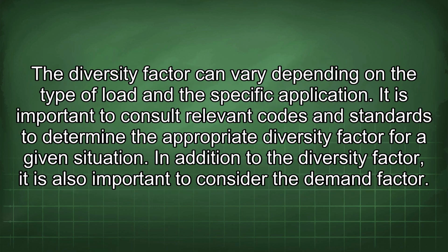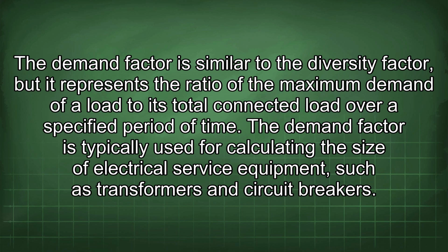The diversity factor can vary depending on the type of load and the specific application. It is important to consult relevant codes and standards to determine the appropriate diversity factor for a given situation. In addition to the diversity factor, it is also important to consider the demand factor. The demand factor is similar to the diversity factor, but it represents the ratio of the maximum demand of a load to its total connected load over a specified period of time. The demand factor is typically used for calculating the size of electrical service equipment, such as transformers and circuit breakers.